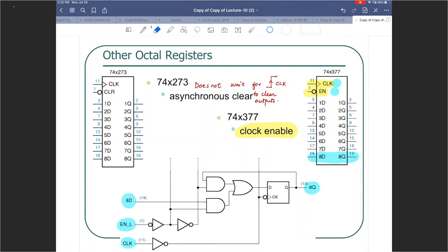Now let's focus on what this is. Let's try to analyze this a little bit. How are we disabling the clock? Well, first of all, it's a positive edge trigger design which is being obtained by using individually negative edge trigger D flip-flops. With the addition of this inverter and the clock being active high, it functions as a positive edge trigger design because that bubble cancels out with that bubble there, logically.